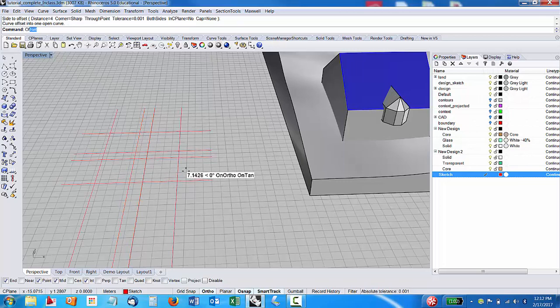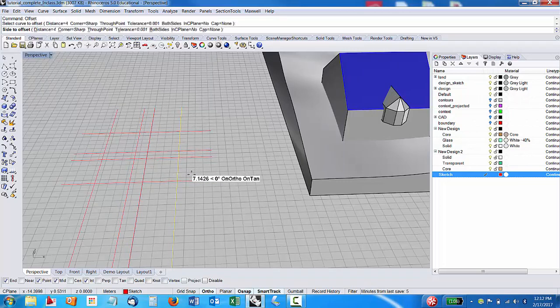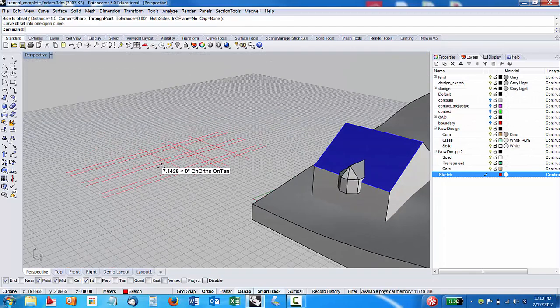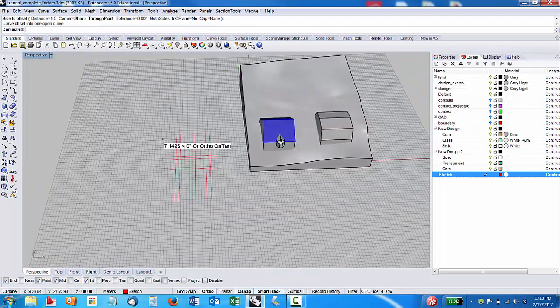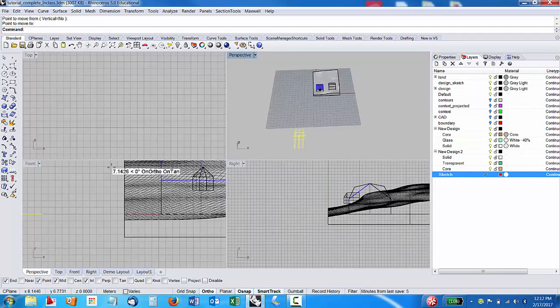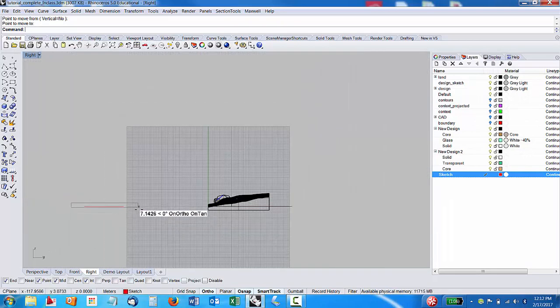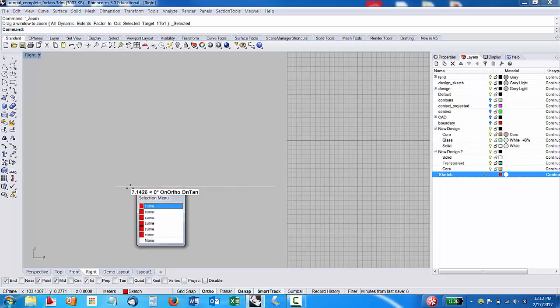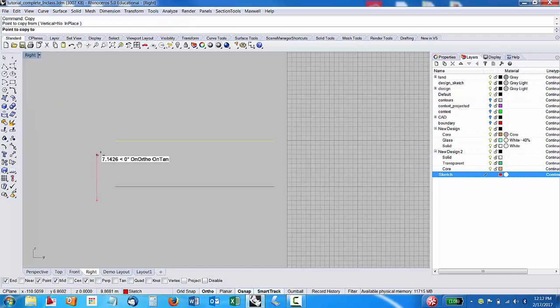And maybe I want to get a little fancy, so I'm going to give myself another little buffer zone here, 1.5 meters. So, it's good to maybe have some kind of structure to work off of. And then maybe I want to work in, I'm just going to move this. Maybe I want to work this in elevation as well, so I can zoom selected here, so now I'm just zooming in and out on that. But this will let me say I want to know my floor levels, so I can just copy a line up, and I can copy it 3 meters for floor-to-floor height.